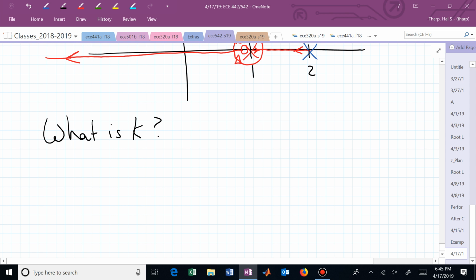And that was now a way to do what? Stabilize an unstable system and still achieve steady state accuracy with reasonable, let's say, behavior. But that's maybe what we'll have to talk about, or maybe I'll talk about that offline. This was a PI controller. If we want to improve the speed of our response, maybe we need the derivative. So I'm trying to now motivate, maybe we now need a PID controller in addition to, or going beyond this PI controller. And we'll pick up at that point next time.